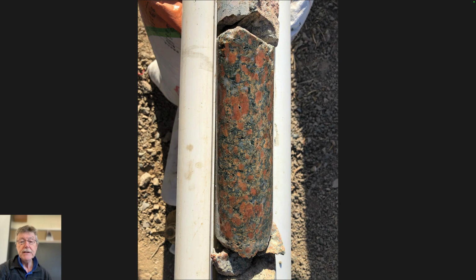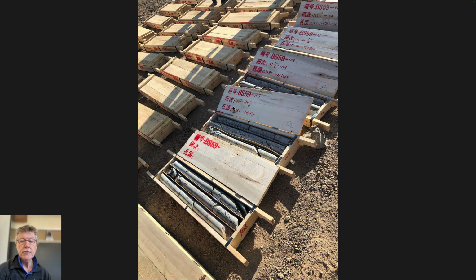And only if you have really fantastic rock. This is a granite, nice big potassium feldspar crystals in the quartz. Typically it would look like this. You take it out of the core barrel, you put it into a core box. You saw some other core boxes in Sweden last time, I think, and it would typically be broken up, mainly with natural fractures providing natural planes where the core will break.